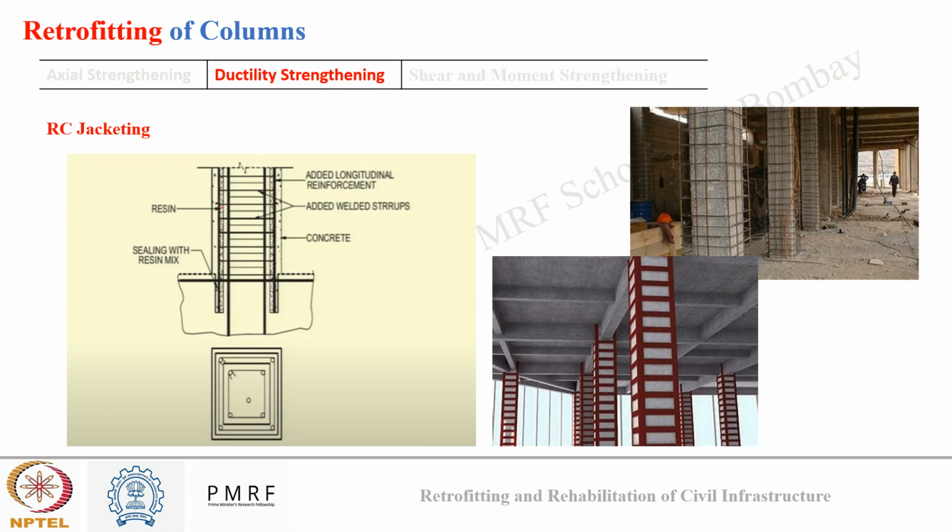Okay, so in the image you can see there was old concrete, and above it the steel cage with the longitudinal reinforcement was provided. In addition to that, the stirrups, the transverse reinforcement, were installed all around. It will run through the concrete also, and it will enclose the steel cage also. And then from the top I can do the concreting, either by placing formwork and doing conventional concreting, or, if my stirrups are very small in diameter and attached to the concrete surface, I can also use the shotcreting method.